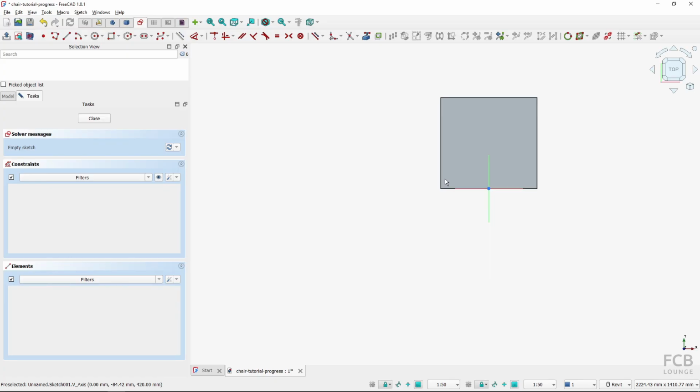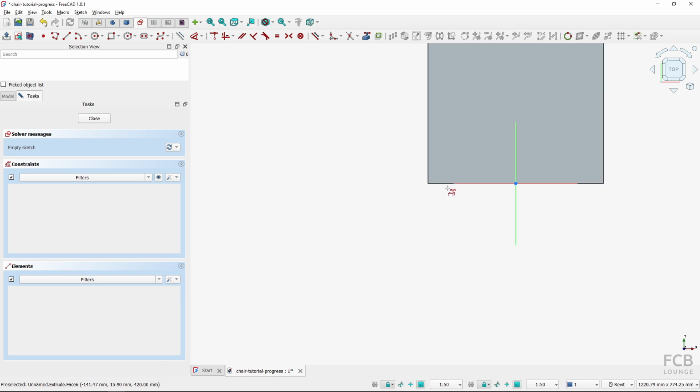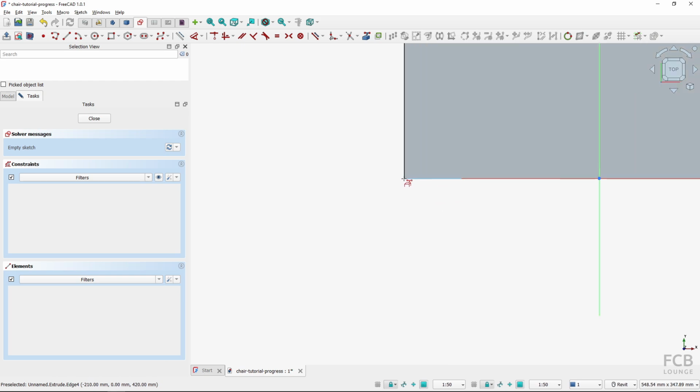So now here I will create the rectangle, and because I want to snap again to this point, I will choose to create external geometry. And if I have my mouse here, actually I want to be careful to have just the point imported.